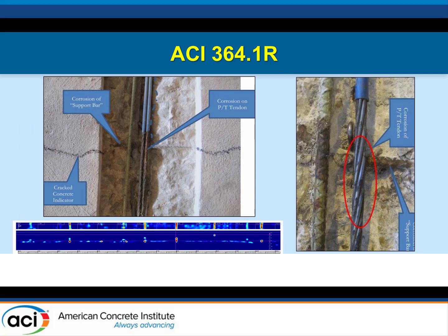So the point I want to make is, whereas the GPR is one of the vital tools that we use in evaluating post-tension structures, what we're doing inevitably is we're going to go in and we're going to cut probe pockets so that we can examine the reinforcing up close. So in this case, we found there had been broken tendons that were obvious in the structure. We started looking around and running the GPR scans. We also found that there was cracking patterns that made sense for us to go look there.